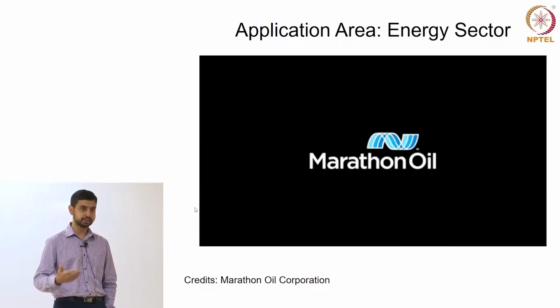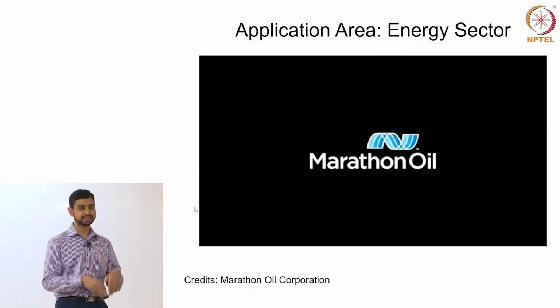which you need to, so that you can enhance the permeability of these shale formations, so that natural gas can be extracted in an economically viable manner. Then you're also injecting sand particles so that the fractures remain open once you create them, because otherwise the earth is so compressed that you may create a fracture, but as soon as you stop pumping the fluid, they'll all shut, and that basically makes this entire process futile.